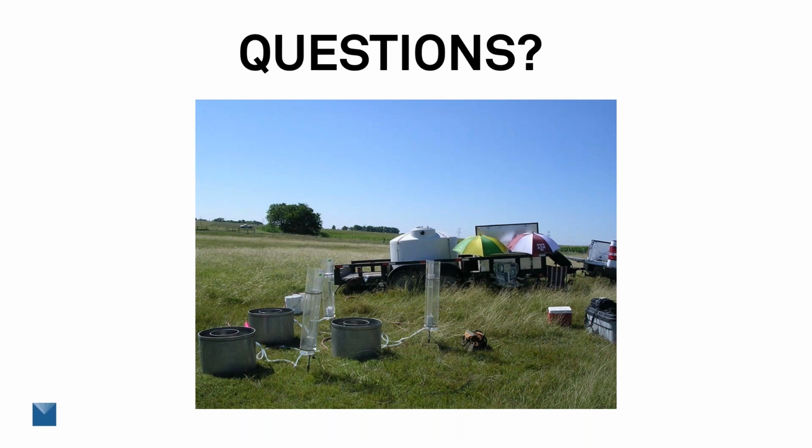Yeah, that's a really good question. And actually, it's interesting in talking with some people about some of the work that they've done looking at different land uses and those types of things. Even in the field, you obviously would expect to see an impact from the root distribution and the amount of roots that are present in the soil, because they do impact the soil's ability to transmit water. But it will ultimately impact the measurement. So if there are root channels or roots in the soil, it may decrease the soil's ability to infiltrate the water. But again, this is what's present in the field.